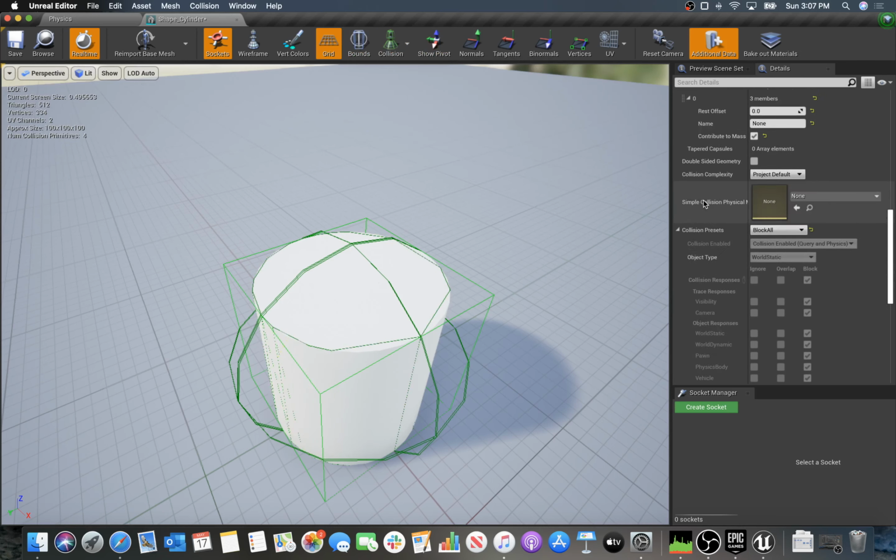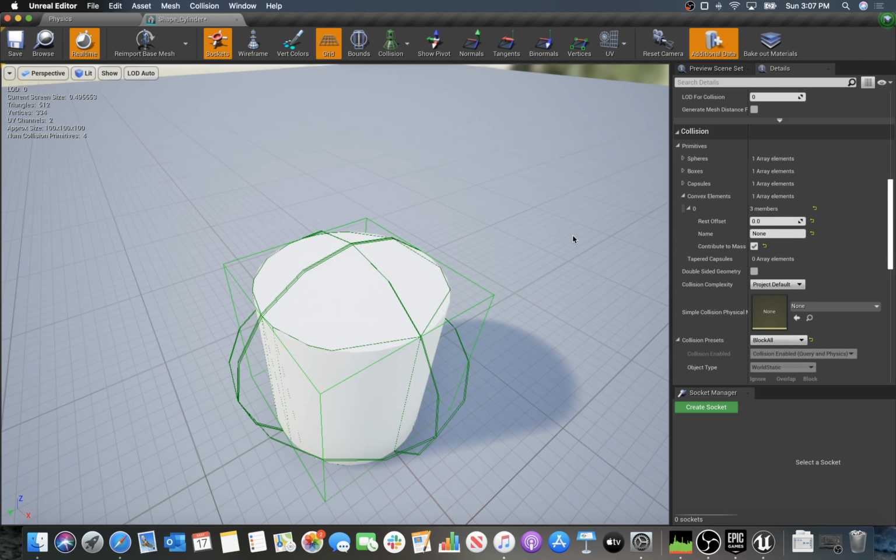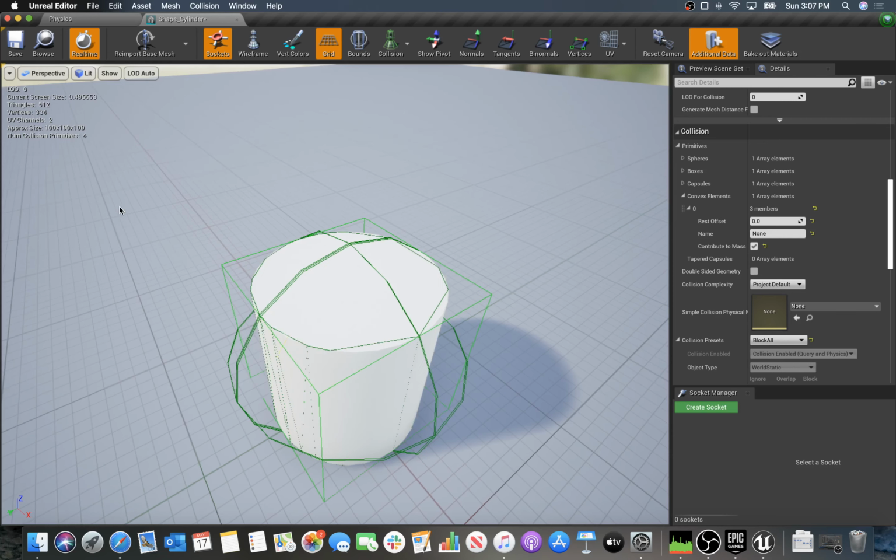And in fact, you can set up all the settings on it by default so that it has the collision settings already set. So every time you use that mesh, it's ready to go. And so that's sort of the last bit of things that you'd like to know for just getting Unreal's physics engine to work for you in a nice way.